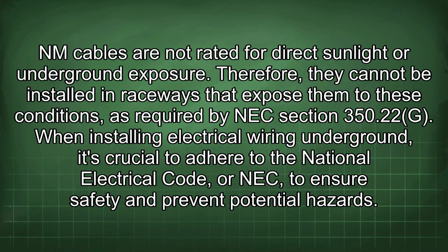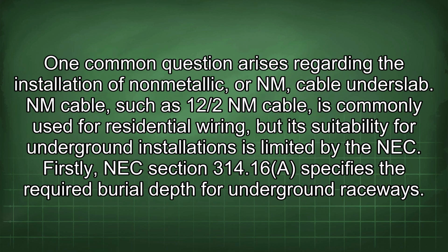350.22g. When installing electrical wiring underground, it's crucial to adhere to the National Electrical Code, or NEC, to ensure safety and prevent potential hazards. One common question arises regarding the installation of non-metallic, or NM, cable under slab. NM cable, such as 12/2 NM cable, is commonly used for residential wiring, but its suitability for underground installations is